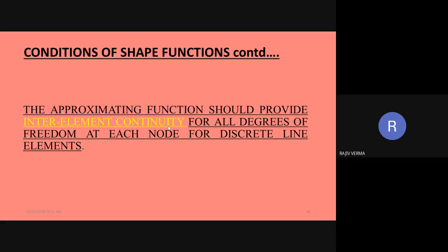The node which was common between the two elements initially is going to remain common between the two elements even after deformation. It does not crack. Therefore, the mathematical expression should provide for the condition of inter-element continuity for all degrees of freedom at each node.